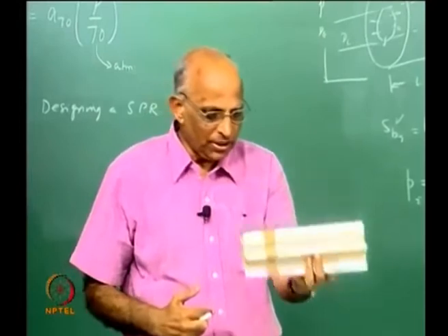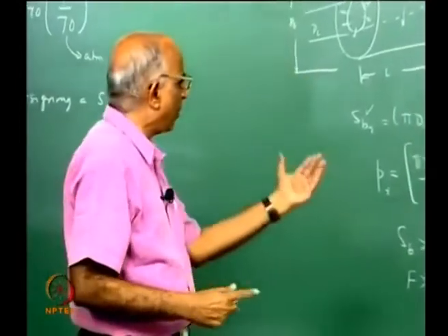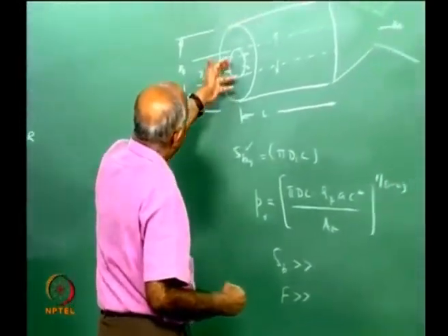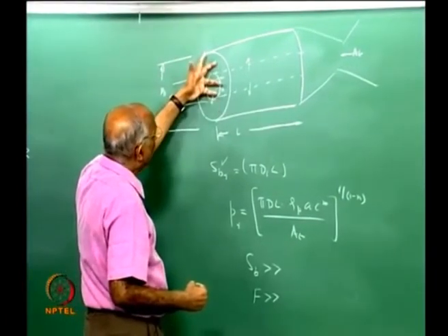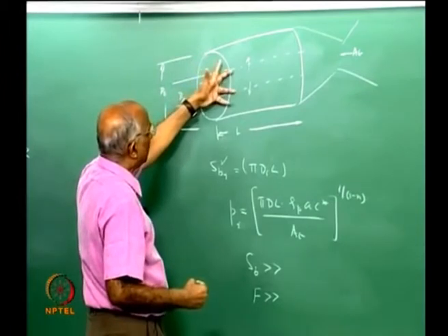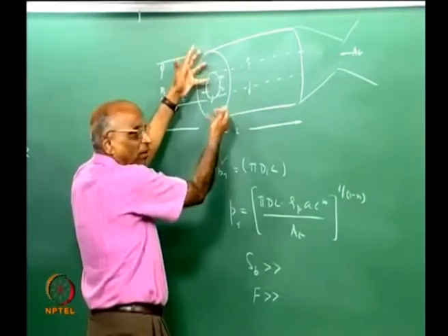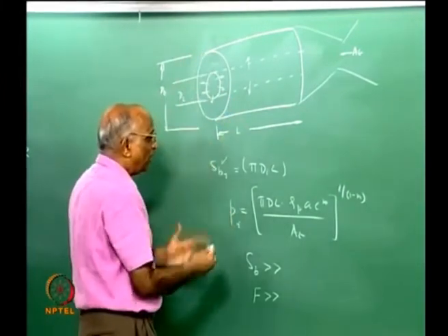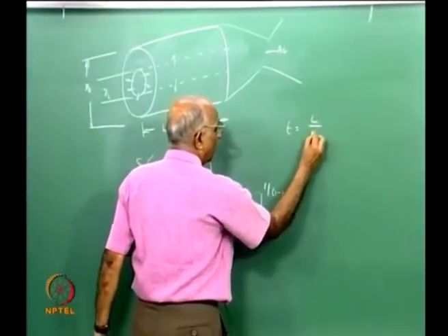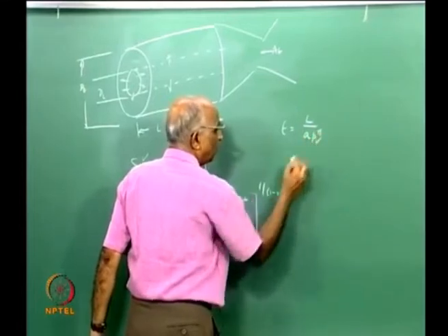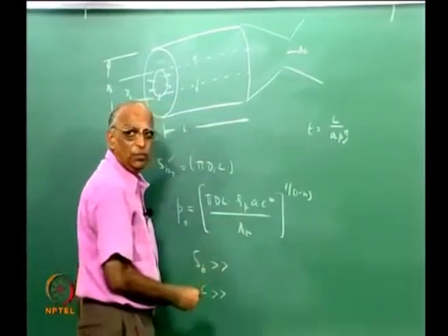But however, before doing this problem, let us do the simple problem of maybe a radial burning grain burning from inside to outside. What is the value of pressure and what is the time required for burning this? Because in the case of end burning, what did we get? We got t equal to length divided by a p^n. We knew how to calculate the pressure, I knew the time taken to burn it.